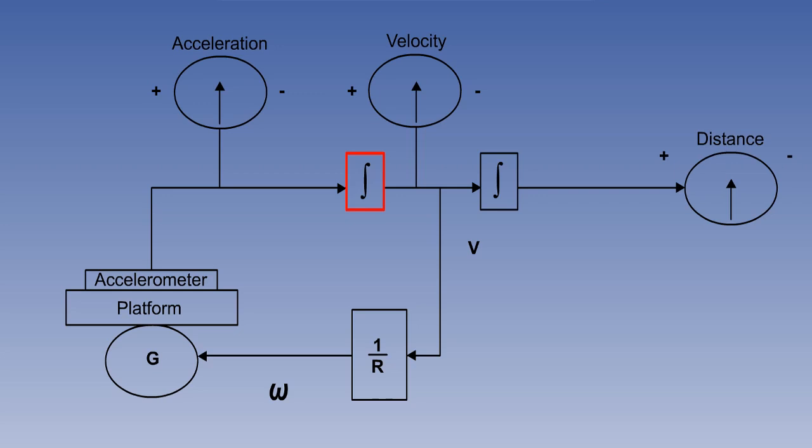The acceleration goes to a first stage integrator, where it becomes velocity. The velocity goes onwards to the second stage integrator. But again, we can monitor it with our next imaginary meter. And again, vertical means zero output, left means positive, and right means negative. Here's the second stage integrator, with its output of distance, for which we used the same convention. It's just easier in this diagram to see a needle presentation than changing digits for latitude and longitude.